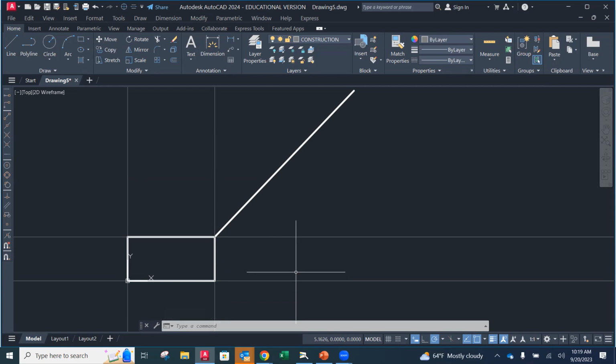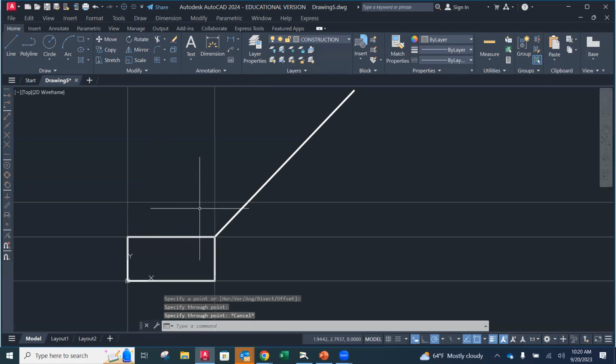The next thing I want to do is set where I'm going to start my next view. So I'm just going to go a distance up. If you remember from when we started AutoCAD, they would do like the 1.5 inches between, just a distance right now, because we know that because of CAD, especially when we add our dimensions, we have that freedom to move things apart when we need to. And we don't want, when we're constructing, for them to be so far apart either. So I'm just going to grab a construction line, and I'm going to go about this far apart. Okay. And I'm just going to make a horizontal line. Now what that sets for me is the front corner where I'm going to come down for where my right side is going to be.